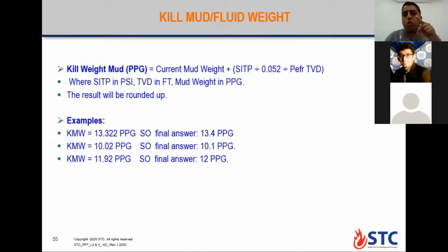But in forward circulation, you have too much contamination, oil and water inside the annulus area. At the same time, reverse circulation gives you lower pressure at the surface, and while pumping, all the gas and oil come out first from the hole, so you can control the well more easily than with forward circulation.